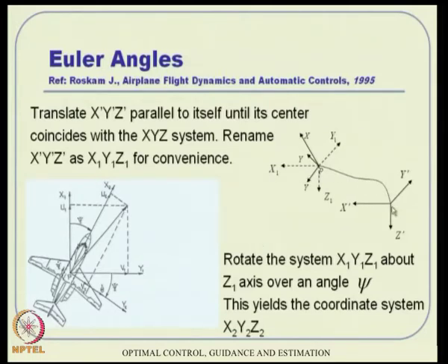First, we take this coordinate system, simply translate it over there, and we have to use a different notation so as not to get confused. So this x prime, y prime, z prime is rewritten in terms of x1, y1, z1. This is simply translated over there, nothing more. Now, this x1, y1, z1 I can rotate with respect to the body z axis, so that the entire xy frame that was there previously will try to coincide with this xy.